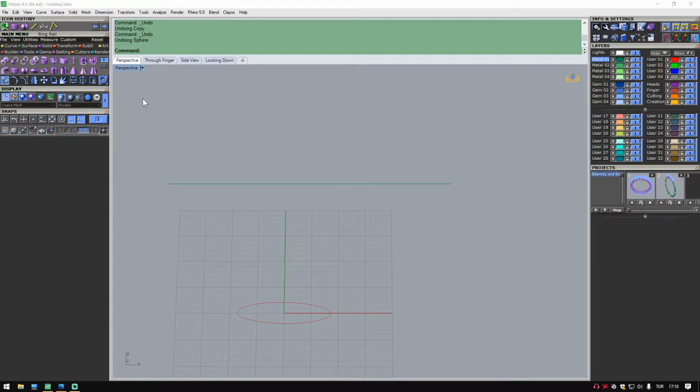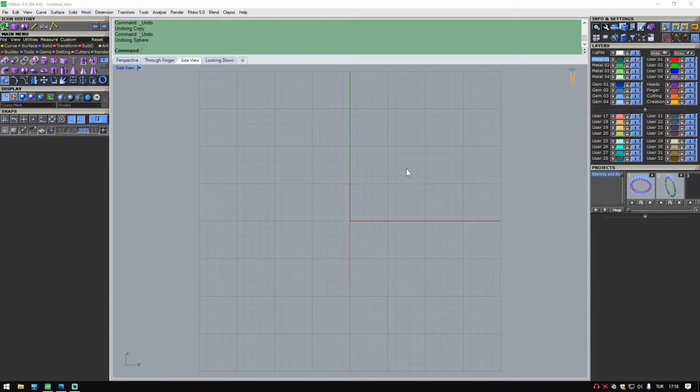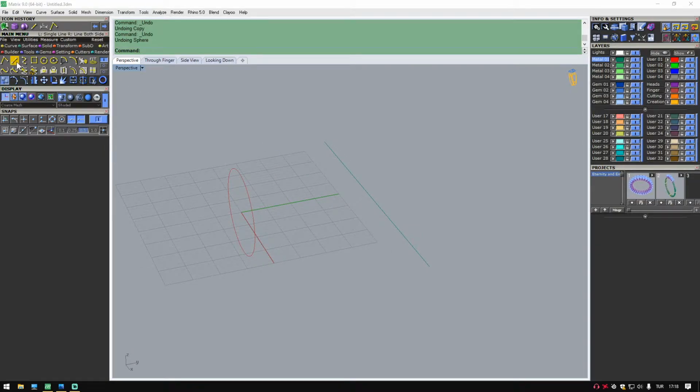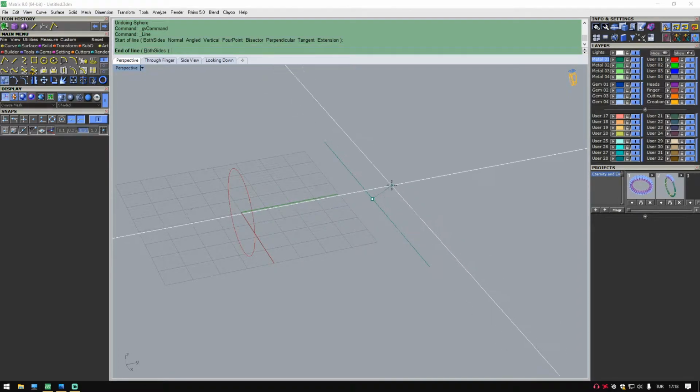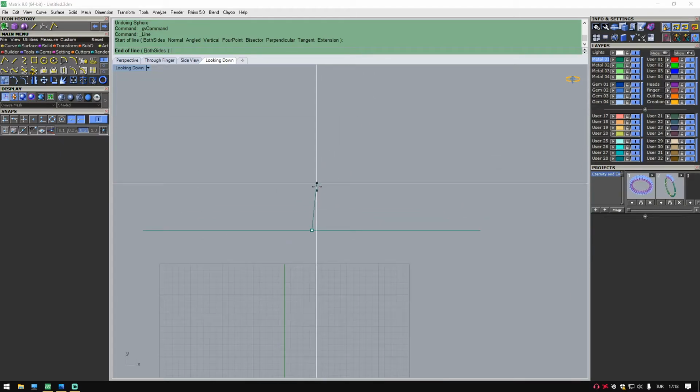And then I want this ring on top to be 2 centimeters, like so. When you check in your side view, the ring from this end to this end, I want it to be 2 centimeters. To do that, we will need to get a curve, a single line, and press here on the mid. Okay, now we have the curve. I'll go into looking down to see things better. Now it's working one way, up or down, but I want it to be two-sided. So I'll click both sides.